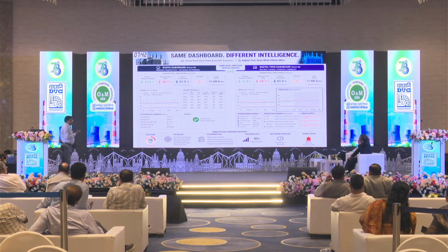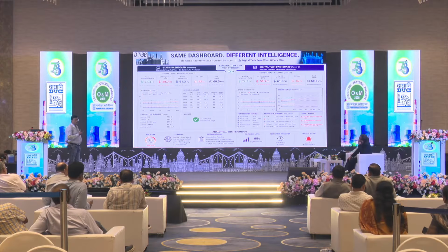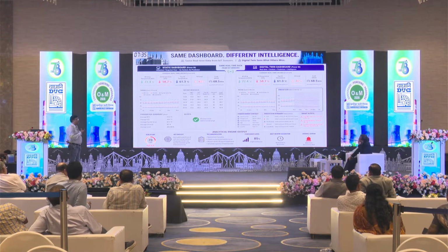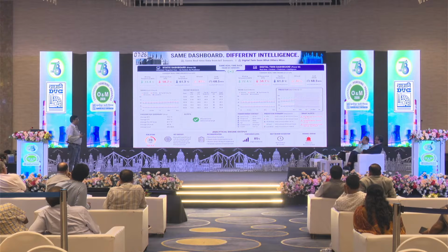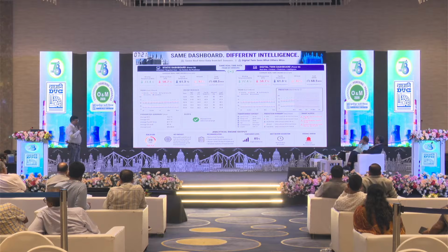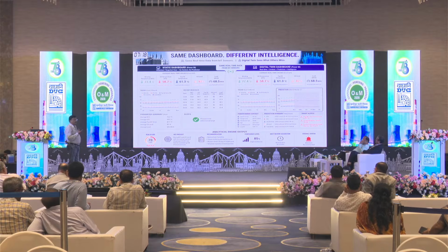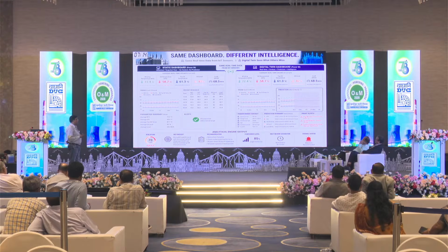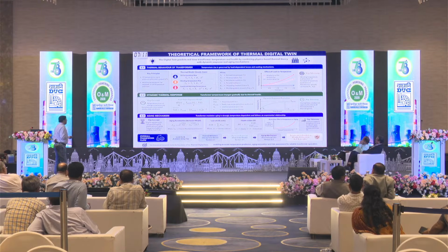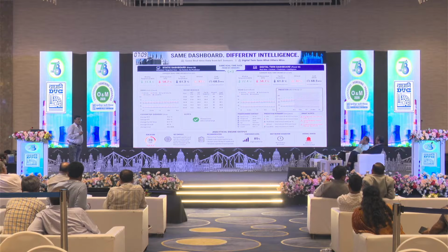The operational engineer can also do scenario-based simulation, that if I increase the load of the transformer by 40-50 megawatt, what will be the OTI and WTI. So it will be very important for the operational engineer as well as for the maintenance engineer. If he finds any deviation of OTI, WTI from a standard parameter, then he can take the decision that maybe some fan has been off or some hotspot has developed. So this is all about the introduction of digital twin.